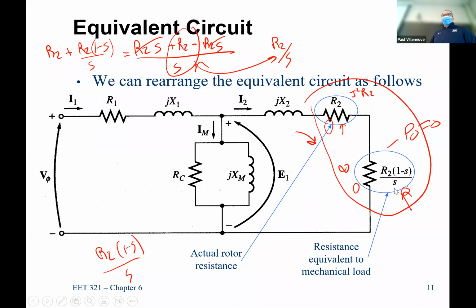Yeah, the lower the value of slip, the lower I goes. So you have lower losses in your machine the closer you get to synchronous speed. You can't get to synchronous speed because it won't run, but that's why the machines run so darn close to synchronous speed. It's because they're at their most efficient.